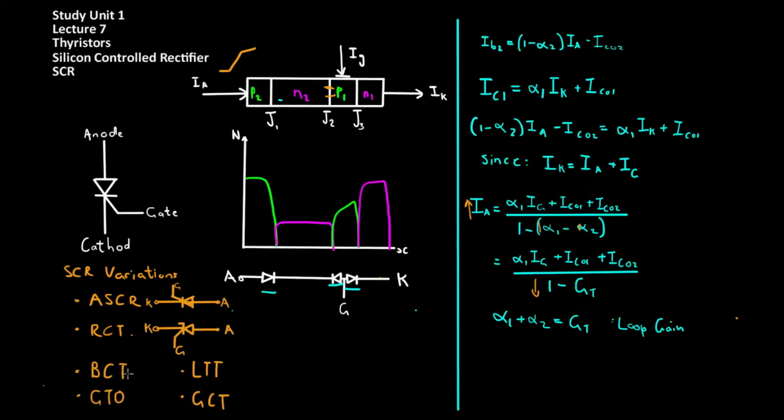Finally, examples of other thyristors are a bidirectional conducting thyristor, a gate turn-off thyristor, a gate commutated thyristor, and a light triggered thyristor. These devices all have the same fundamental function as a silicon controlled rectifier, but have architectural structural changes to suit some other application.